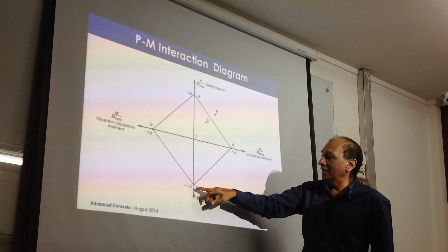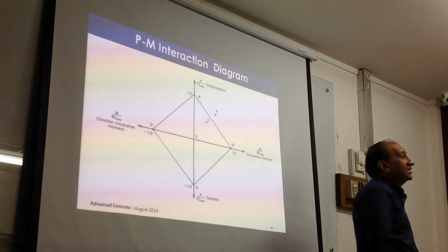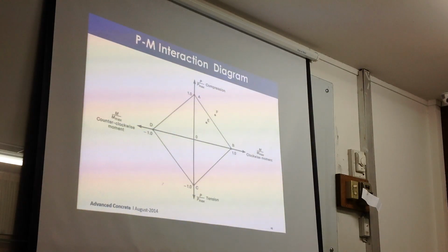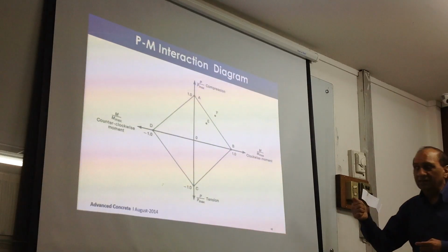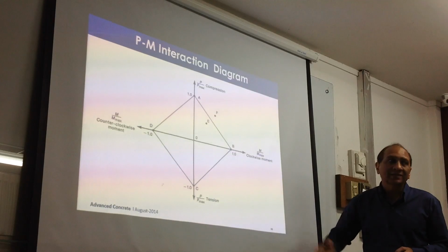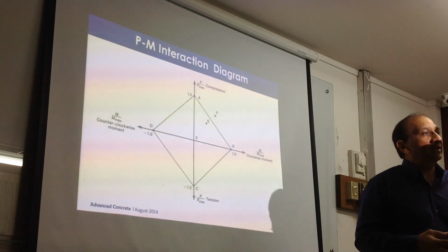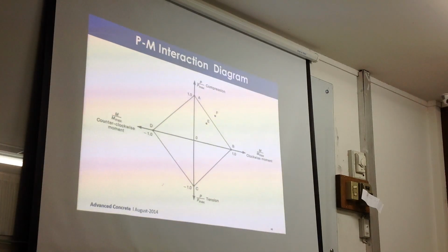So we can normalize it, and then we can calculate the points based on the normalized numbers. Normalized means we divide them by the maximum. Then it becomes non-dimensional. It just becomes a ratio. So it's easy to check the ratio directly because it's normalized. So we can get the capacity, the DC ratio, from such curves. You can plot these curves in real numbers, or you can plot them in a normalized manner, and then from there we can calculate the capacities.